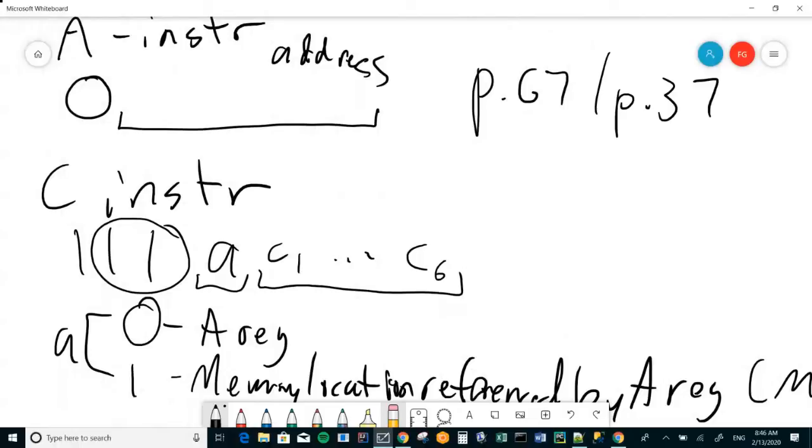In fact, you should. The ALU was designed with this specific instruction set architecture in mind. It's intrinsic to the ALU. And so that's what enables you to do that. So those 6 bits are just going straight into the ALU. This is controlling an ALU input. So far, you might notice we haven't changed anything, right? We've routed 1 bit to decide on an ALU input, 6 more bits to tell the ALU what it's spitting out.